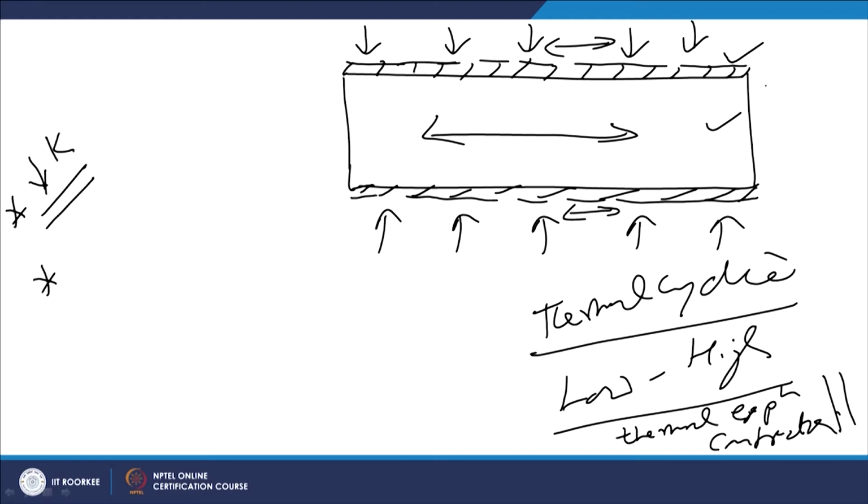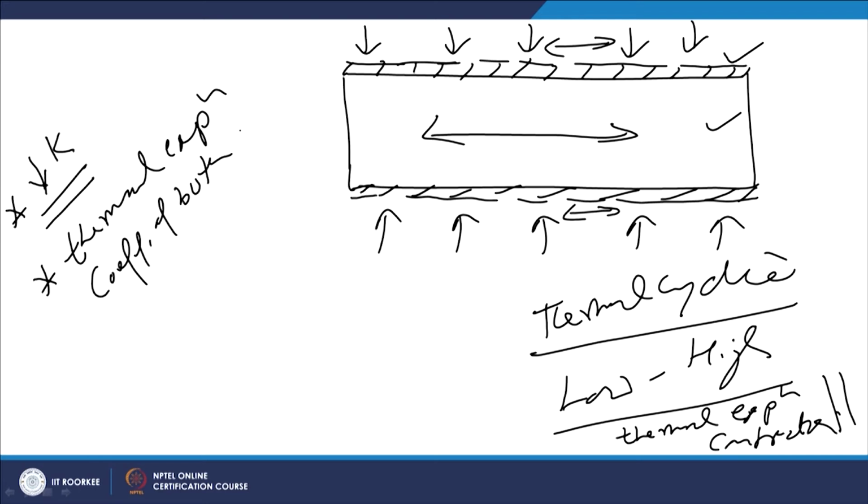And this will happen only if the thermal expansion coefficient of both the substrate and coating material are close to each other.